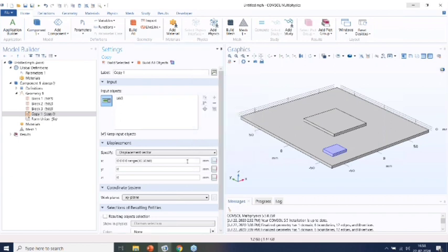Add, and the next displacement is 30. So the same object I want to get repeated at different displacement. The first 4 are just 0, 0, 0, 0 only, and next I am specifying some displacement in the X direction. However, as of now, I am not providing any Y displacement or Z displacement.